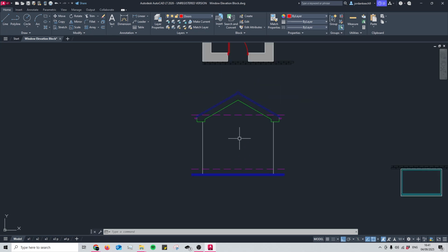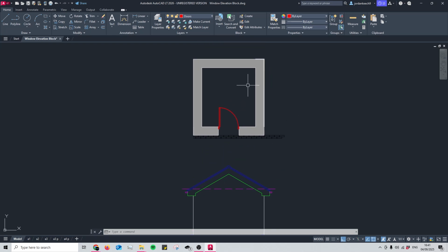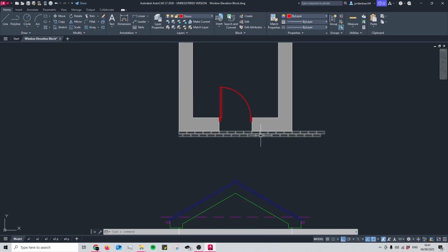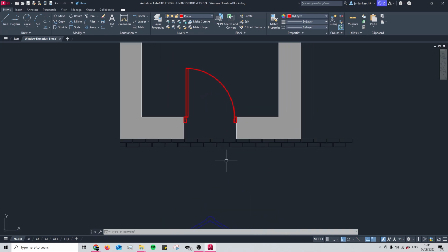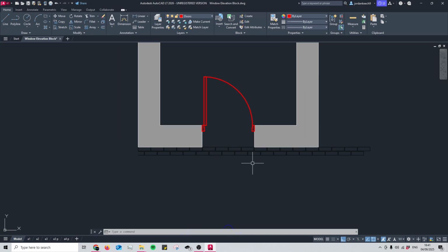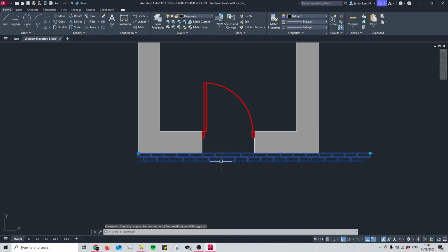Before I begin drawing on the door though, I need to check that everything within my plan is sized correctly, meaning everything is a brick dimension. So what I mean by this is that the overall size of the house and the door's aperture here fits between full bricks. Now you could run the maths on this and calculate the correct distances, but I have this brick block that visualizes the bricks, meaning I can just check visually rather than pulling out the calculator. This saves me so much time considering I do this every day.